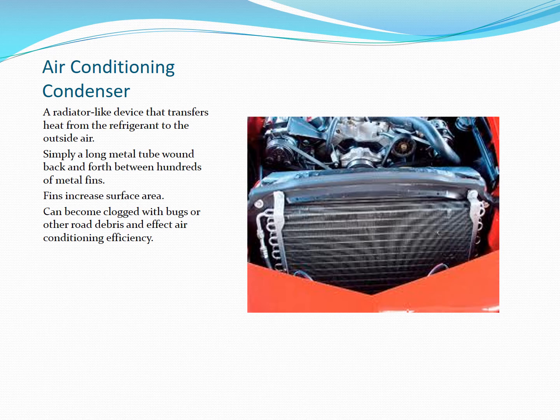So later on when we talk about diagnosing these systems, that's one thing that you need to be very aware of. It's a very common problem that these condensers get their fins folded over from impacts, or from small bugs over lots of miles, or the condenser gets blocked with something else. Maybe it's somebody that puts a piece of cardboard in front of the grill for the winter time so that their heater warms up faster, and they forget to take it out.